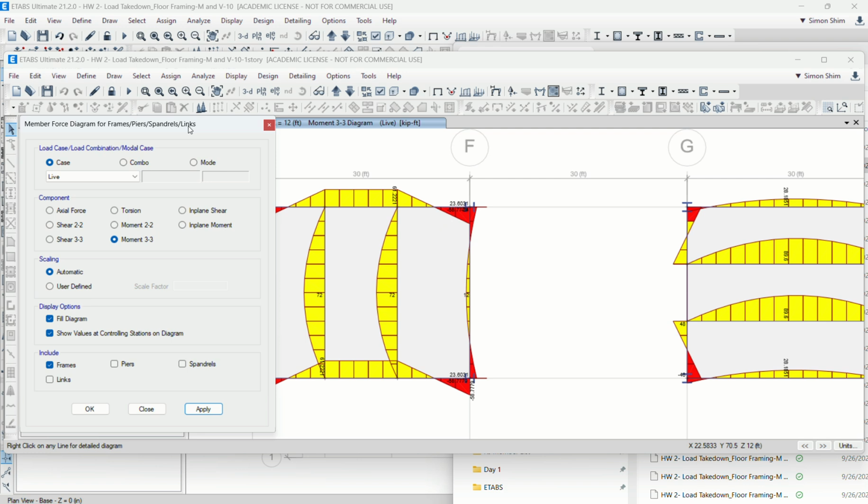So we confirm the live load, obviously we calculated it, right? WL squared divided by 8. Remember this. PL divided by 4. WL squared divided by 8. Moment. Remember this. These are only two formulas, especially WL squared over 8. You're going to cover most of your engineering work, because most engineering problems are typically slab and beam. Right? Slab and beam problem.